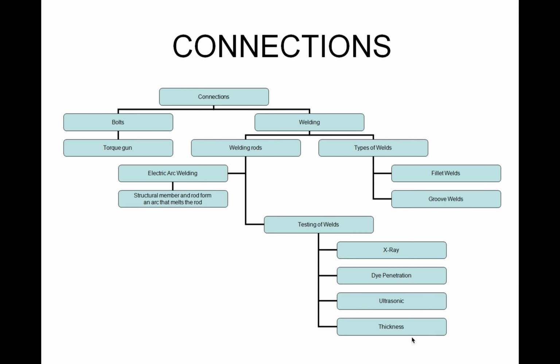The other way we do make connections is through welding, and welding is a much longer process to make a connection. Generally, if there's welded connections, you'd like them to be done in shop, because welding is weather dependent. And when I say weather dependent, depending on the type of welding you do, there's these type of powders that are part of the welding. They get easily affected by wind. Your welding rods need to be dry.